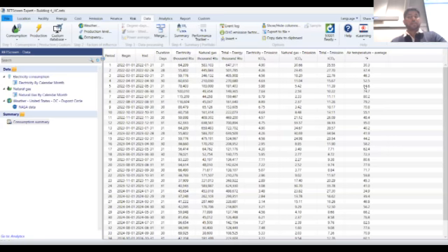And there you go. I get the air temperature average for those particular months. This is just getting the data set ready for regression analysis. Now, question for you guys. We can either compare natural gas with heating degree days. We can compare electricity separately with cooling degree days and understand the electricity savings and natural gas savings separately. Or we can have a regression analysis for the total energy and compare it with air temperatures and get total savings. What would you like to say?